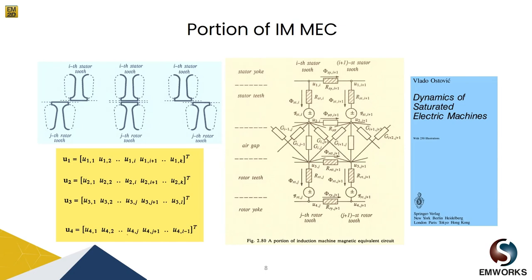If we increase the number of elements in the equivalent circuit method, we can get a better resolution. But consider that our purpose is not to use a complex circuit, because our aim is to have a simple solution for dynamic simulation of the induction motor. So this equivalent circuit is good enough for these purposes.